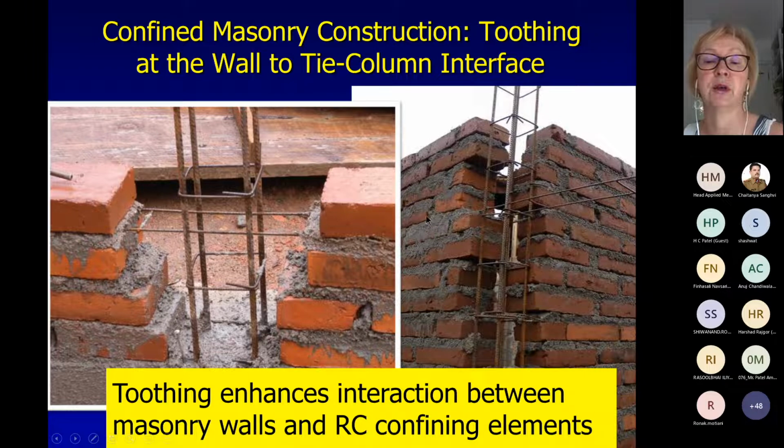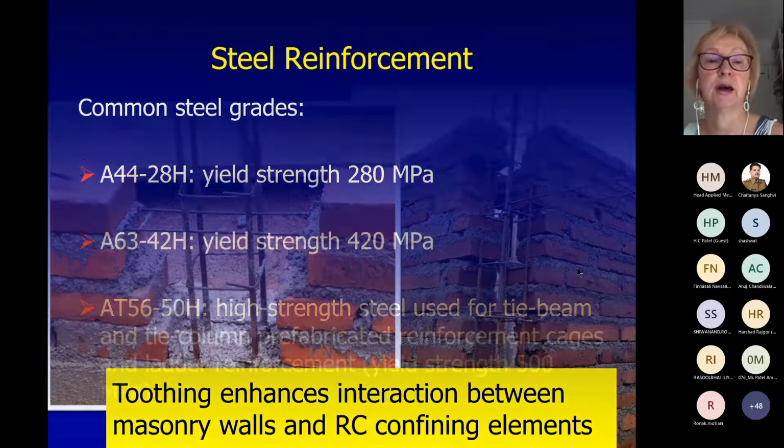So they might have reinforcement continuous along the wall length. So it's not just at the intersection locations, it is a horizontal reinforcement. But I cannot see a location of other bars. So anyways, it is not heavily reinforced in horizontal direction. And these are very small wires practically, as you can see very well from these photographs.